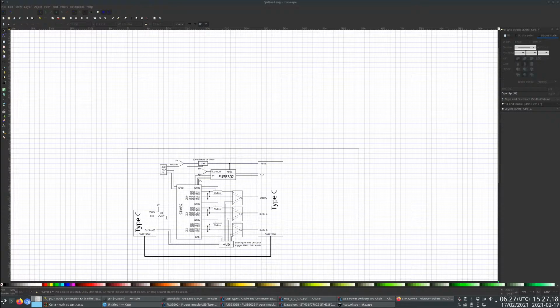Yeah, the thing is, I was thinking about it being a USB PD host. But if it's a USB PD host, then what about VBus switching? Okay, then it switches VBus on, but then we need to switch VBus to the target, and if we pass through CC and the target requests a voltage change, then our voltage changes.